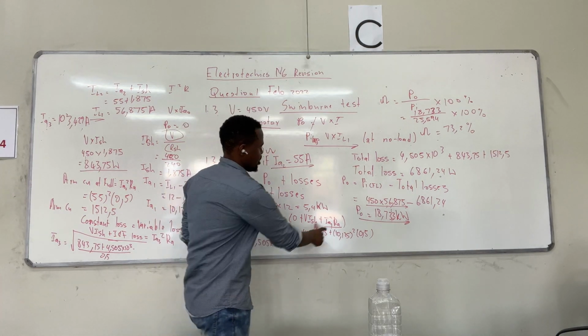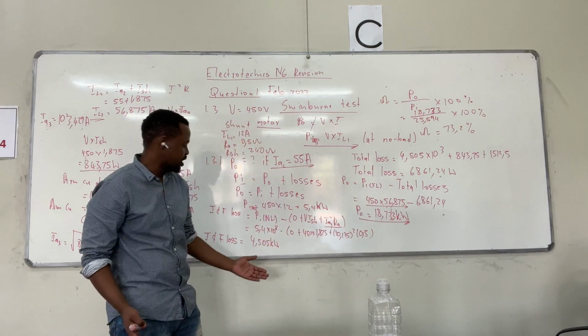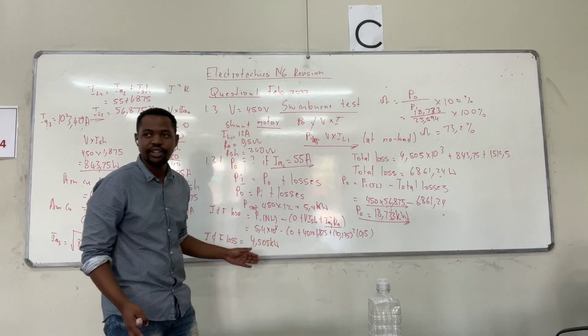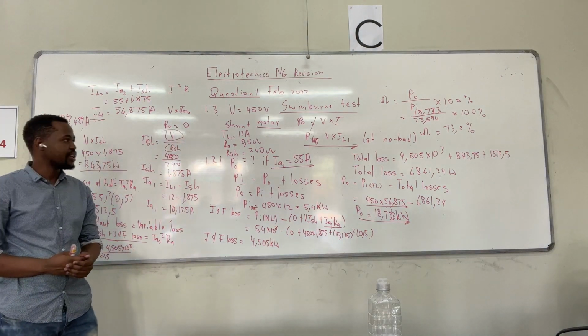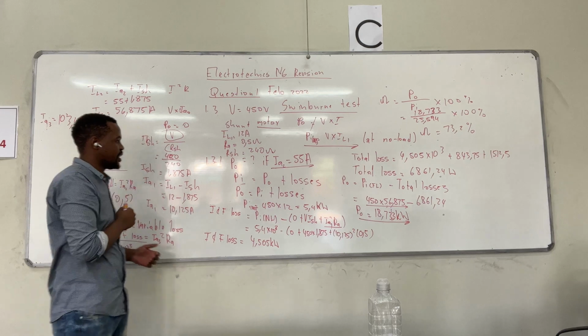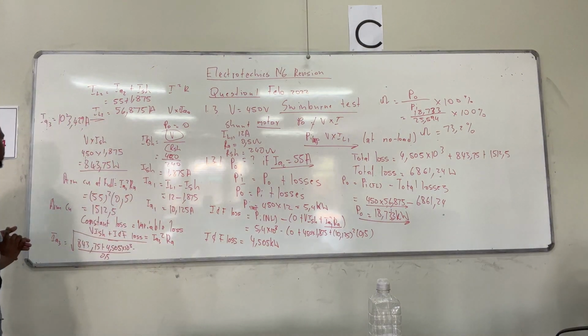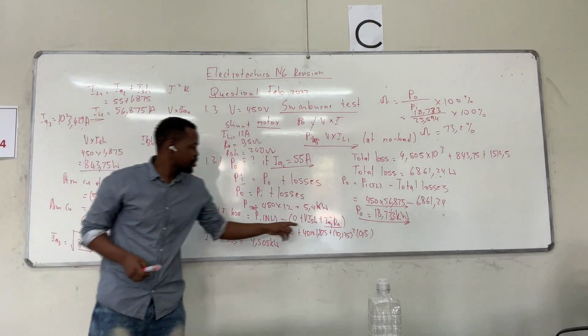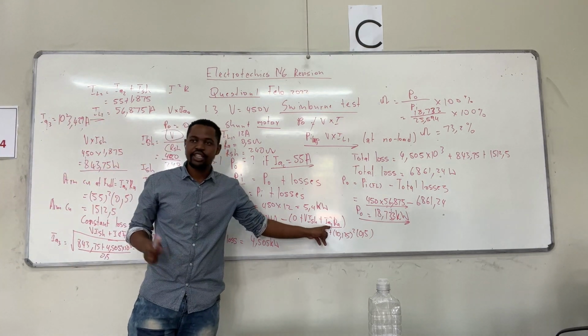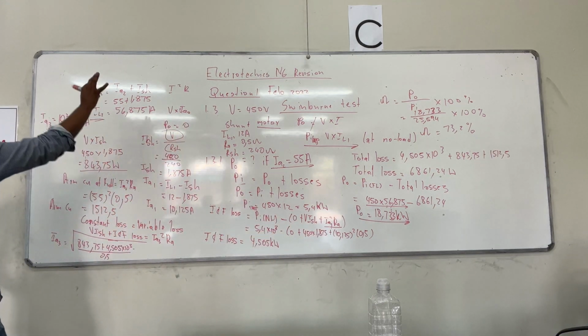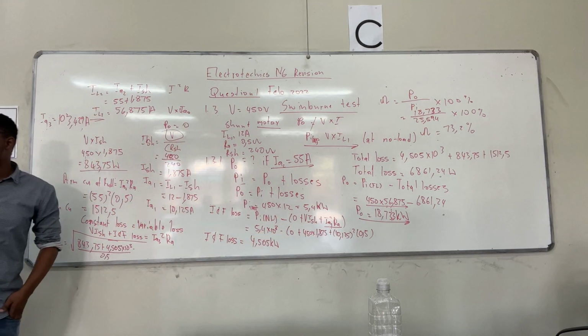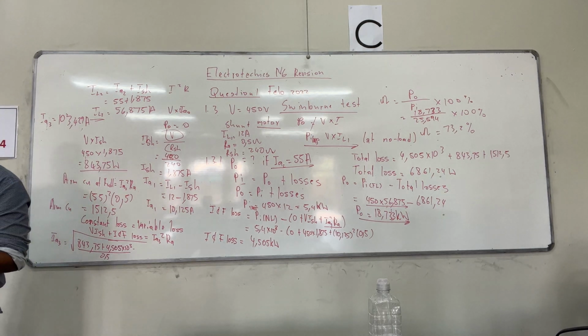Here is the formula we need. It helped us find the iron and friction loss, using the armature copper loss at no load. Then we calculated the armature copper loss at full load, because the iron and friction losses are the constant losses.